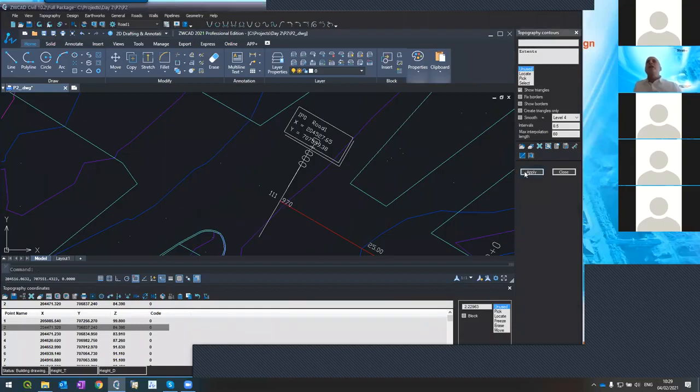So if I show you the triangles, the system will go until it finds the triangle and digitizes the elevation in the triangle. So first of all, digitize the point here at 0, then the next break, the next break, until it went to minus 20 somewhere here, probably. I can measure, but it's not that important. And then the system went to the right and did the same. Then go to the next section and did the same, and so on and so forth.